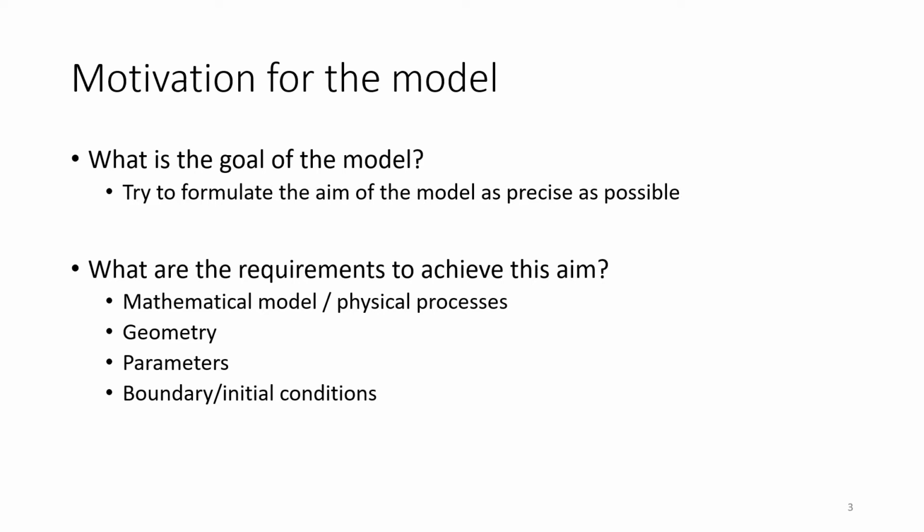Right? And also with this come, for example, parameters. So all those people saying, well, can you model that? They don't have the necessary information, or the information you require is not well enough constrained to design a suitable model. When we're talking about groundwater modeling, we always need hydraulic conductivity and storativity. Right? These two basic parameters that we need every time. And if they say, well, yeah, it's some kind of sand, then, well, you can't work with it, because the value range for hydraulic conductivity and for storativity for sand is so wide, the model outcome could be anything.